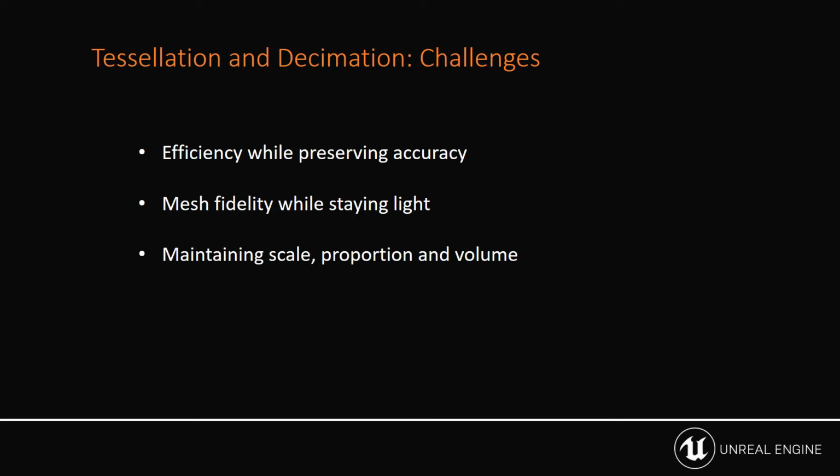That's a challenge. Often we're taking huge data sets and trying to make sure that we maintain the accuracy while keeping the overall geometry load down to be able to work with it in a real-time environment. Of course, we need the basics. We need to maintain scale, the overall proportion, and the volume of the data that's coming from the CAD package. And of course, we are also faced with the loss of data. We may lose things like previous texture coordinates that are important for maybe logos or anything else to be able to hold that texture coordinate on there.